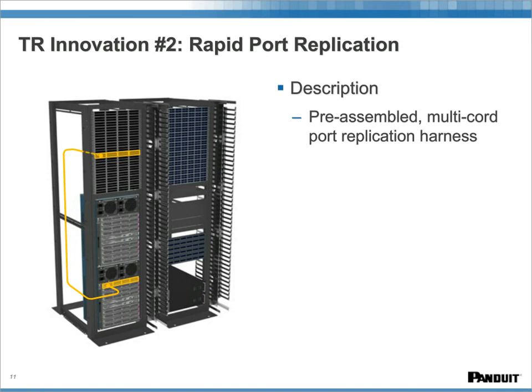So maybe I didn't explain it well enough earlier, but what we're doing here in port replication is simply what most customers do today in implementing a standard 3-connector channel. So the certifications and such would all be the same, and this would fall completely under TIA guidelines, and obviously observing the maximum channel lengths that you do for any copper channel.